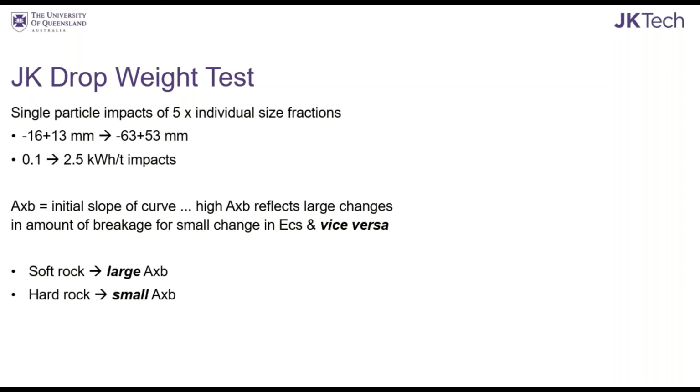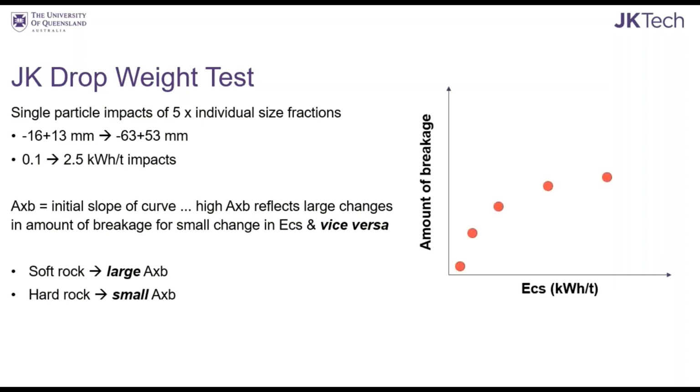And basically, the results are interpreted by a single point on the size distribution curve. That's what's commonly known as the T10. I won't go into that in great detail, but that's what the research showed, the T10, which is 1/10 of the original particle size. It's also referred to as the amount of breakage that's shown on the y-axis there.